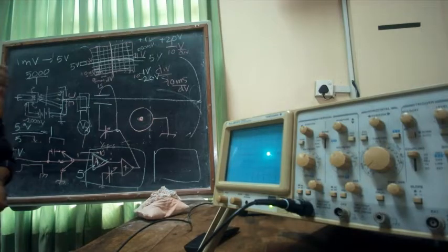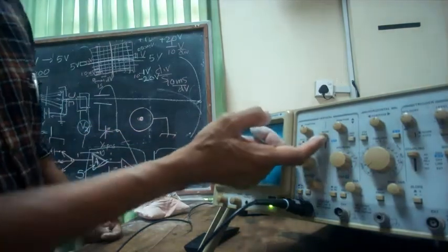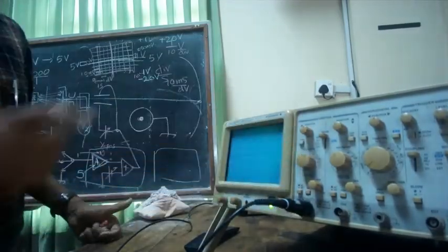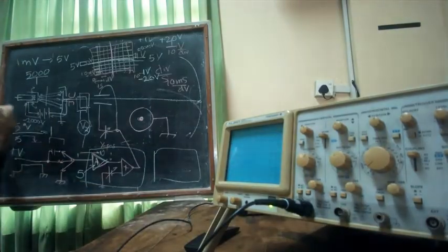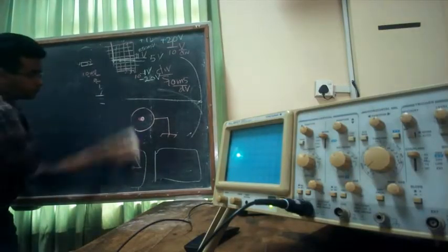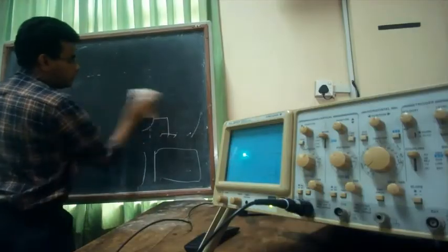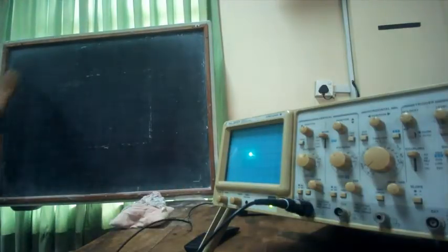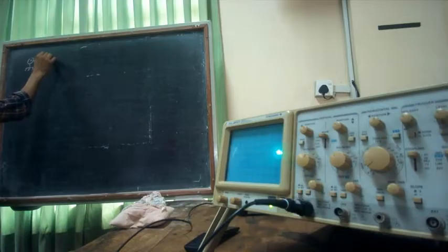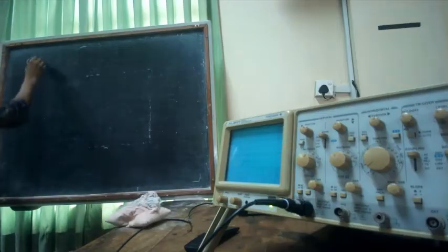So you decide which one you connect using this mode switch. There's a mode switch that you can see which says channel 1, channel 2, dual and add. Correct? So I'm going to erase this because it's getting cluttered. So channel 1, I have the probe outlet. The BNC. This is connected to the chassis, and this is multiplied by a gain. So before that you have these settings, right?